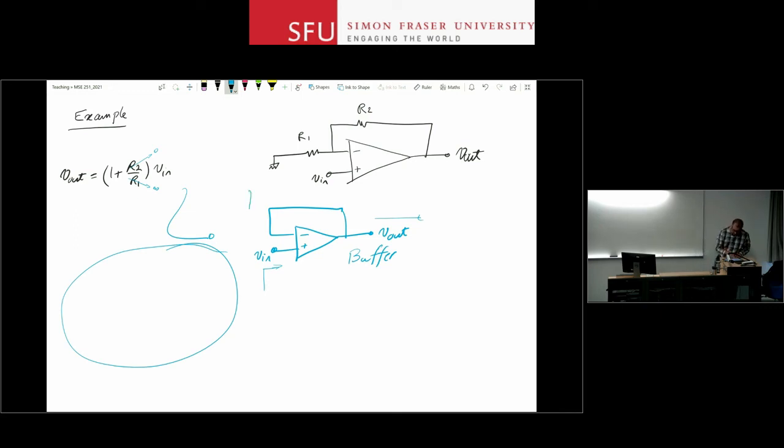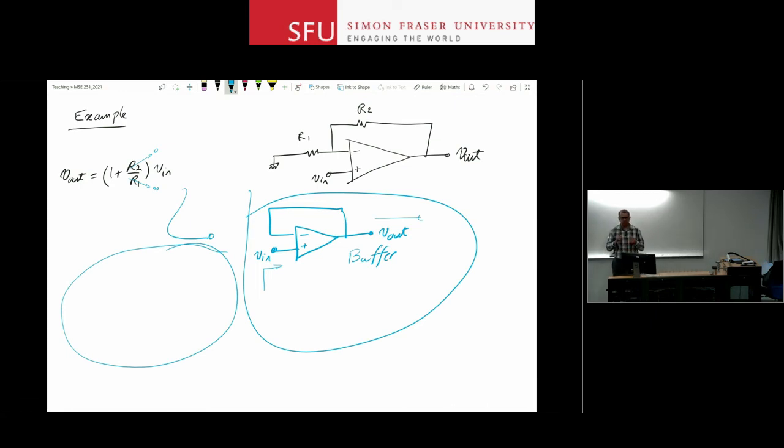So this is a very common circuit, very practical, and you see them a lot. And then, next time that you see this, you think, why would anybody need a gain of 1? If it is a gain of 1, how is that an amplifier? Why do we call it an amplifier? Well, there are two reasons that we may use a circuit like that. The first one is the infinite input resistance and zero output impedance, or output resistance.